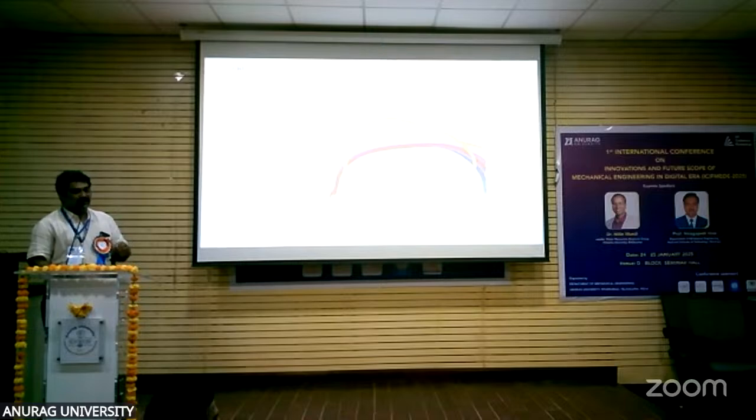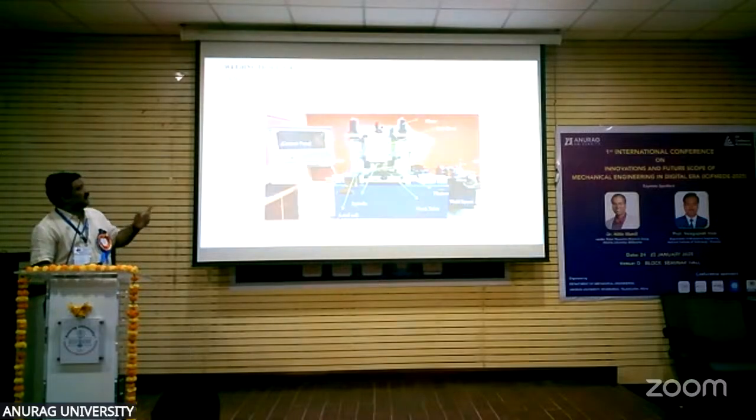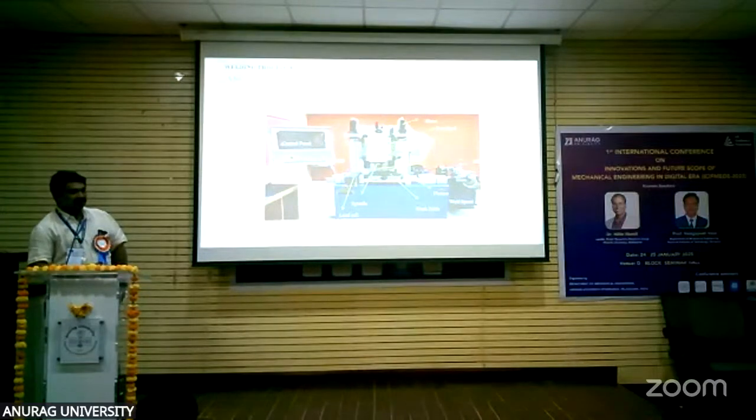And the tool traverse is 26 mm per minute, which is also medium. 36 is the highest, sir. So the middle one is giving the best values with this tool.